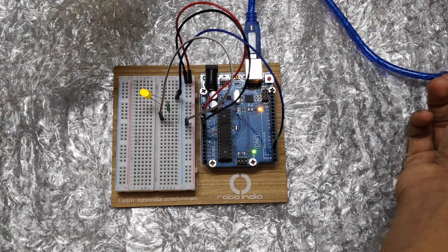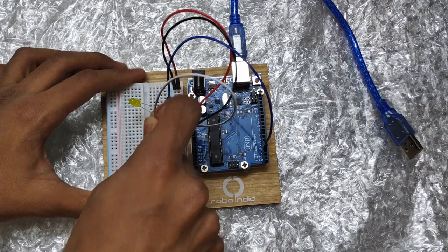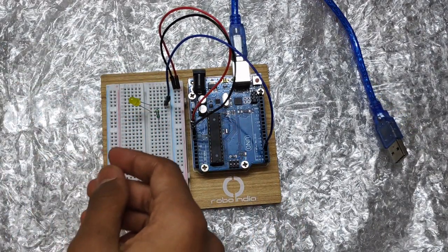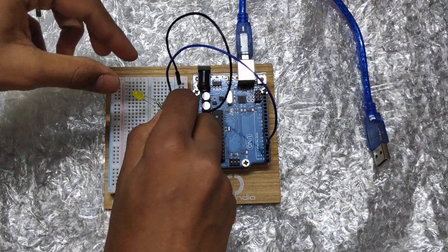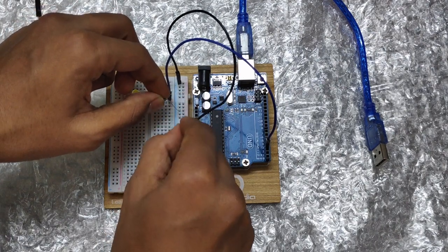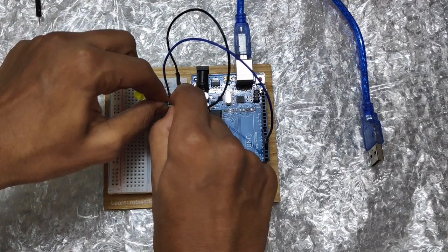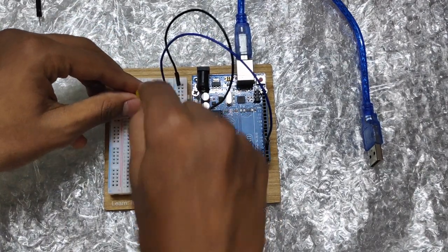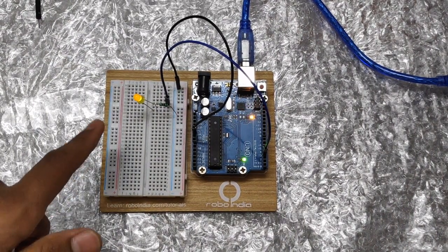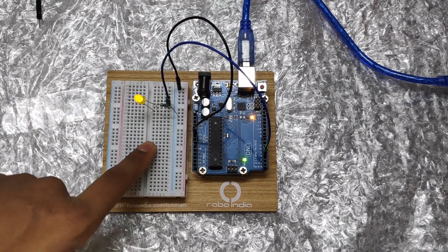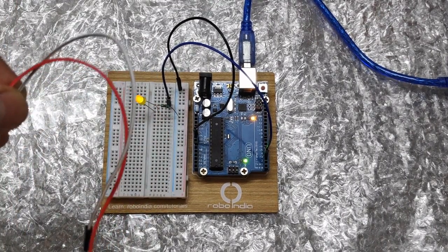So now if you want to customize this and make sure that you need fewer wires, you can remove the white wire and the red wire and connect the 1 K resistor directly to the ground of the breadboard, which is connected to the ground of Arduino. Hooray! The code is uploaded. We customized our connections and still it's working. This looks beautiful. We saved 2 jumper wires.